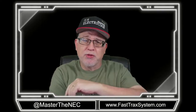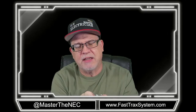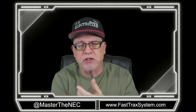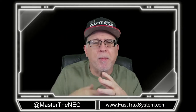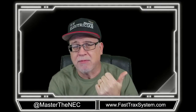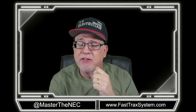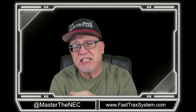So here, part 3 was a short one, but hopefully you watched part 1, got a little better understanding, a high-level view of what determines the neutral point and neutral conductor. You saw part 2, sizing that grounded conductor for practical application based on a load calculation for the maximum unbalanced neutral net current and sizing for that, and then comparing it to 250.102(C)(1).